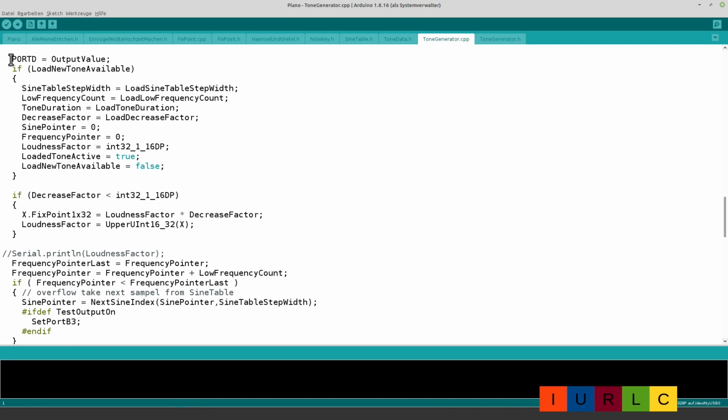Port D is our digital analog converter with the R2R network. This will ensure that our output sampling timing is always constant. If we would do the output after we have calculated within the interrupt service routine caused by the if statements, we will have different execution time, and there will be a jitter caused by the different program execution time on the sampling frequency.